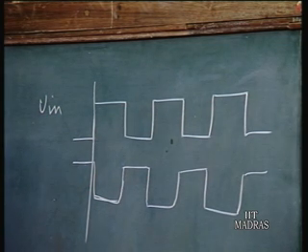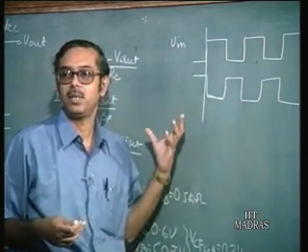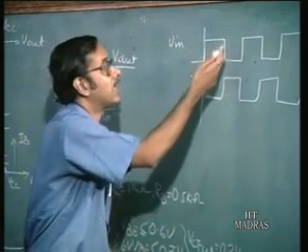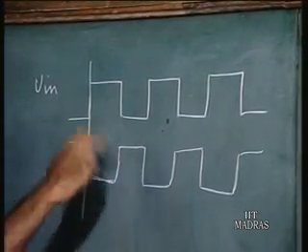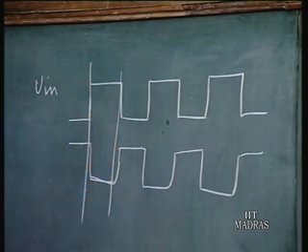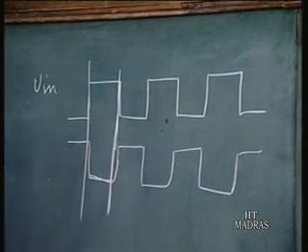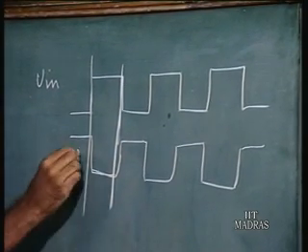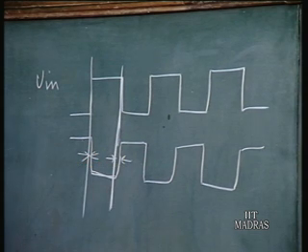That is also a very important aspect of the circuit, and one must design in such a way that this delay is minimum. The other delay is when the input goes from high to low and the output changes from low to high, and you have something like this. These delays need not be the same.